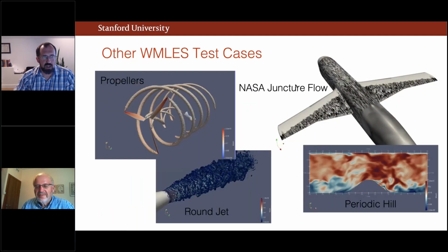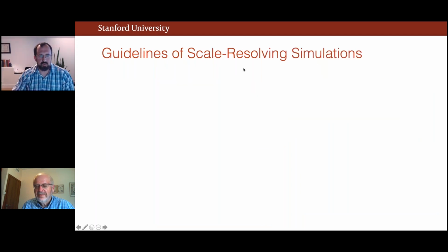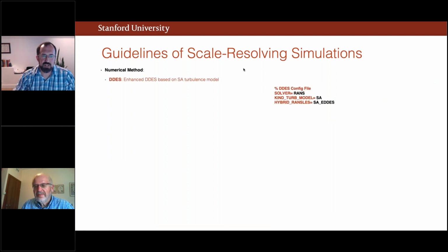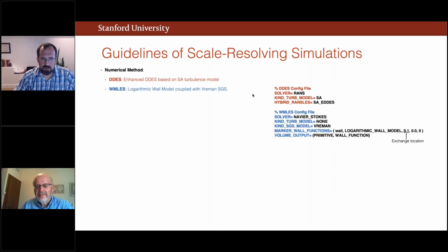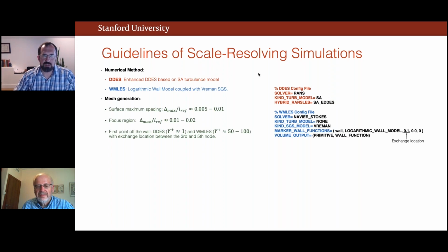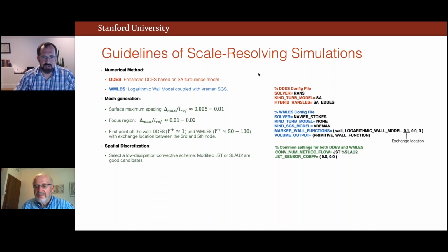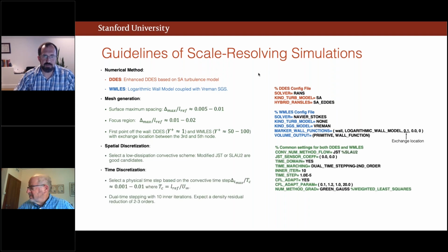Of course, there are plenty of other test cases that have been run using SU2. I encourage you to contact Eduardo if you'd like more information on any of them. And we wanted to close with some guidelines on how to run these scale resolving simulations in SU2. Some tips or advice on numerical methods, the mesh generation guidelines, spatial discretizations, and choice of time step. And you can see the corresponding parameters that you would use in the SU2 config file here on the right.